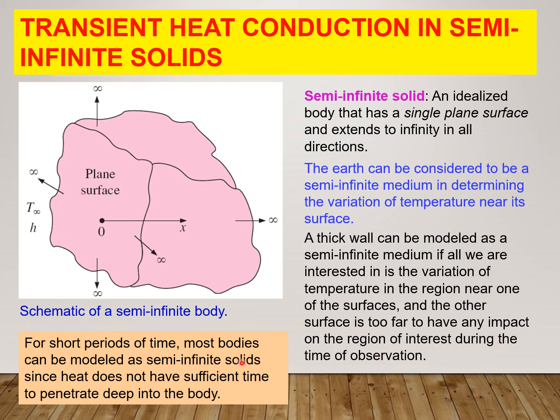For shorter periods of time, most bodies can be modeled as a semi-infinite solid since the heat does not have sufficient time to penetrate deep into the body. The Earth can also be considered as a semi-infinite medium in determining the variation of the temperature near the surface.